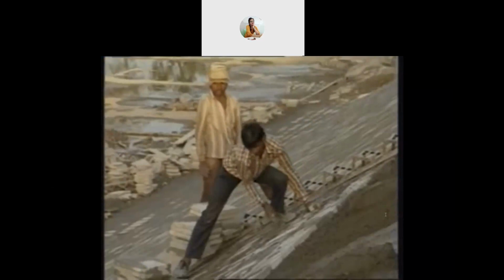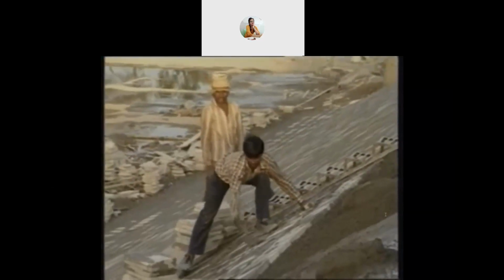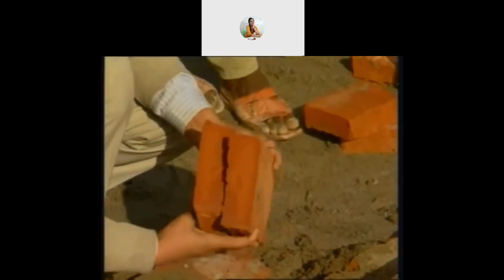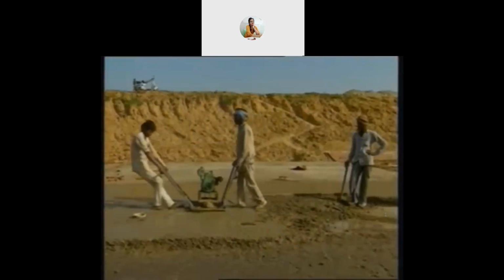In fact, in this area, ample aggregates and sand are available from the River Ganga, but concrete tiles are not that impervious as the clay tiles. Clay tiles are definitely far, far better in respect of abrasion and imperviousness. So now we are doing concrete lining in the bed, and most of the slopes we are having double clay tile lining. By making a new lined canal, we are saving very substantial quantities of water to the tune of 240 million cubic meters, which will result in very substantial increases in agriculture production.